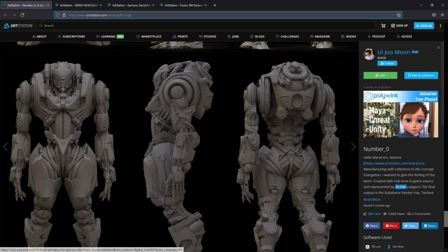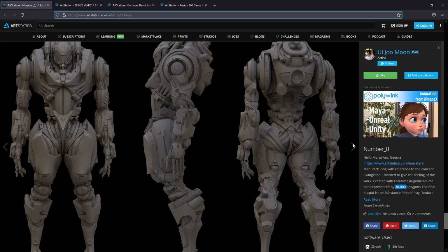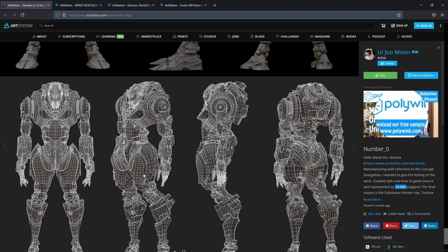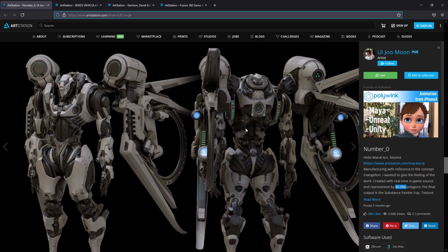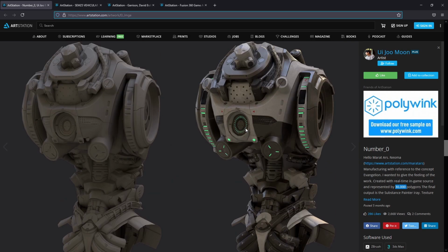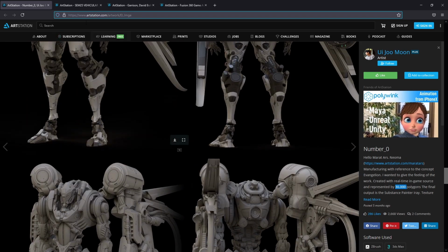He knew the triangle count going in, and he's using triangles all over the mesh, which is, again, completely fine. He's also making sure to have more edges in those smooth corners so it bakes properly, and probably using shrink wrap where applicable. So again, it's a really great example, showing how you can do that throughout the mesh.